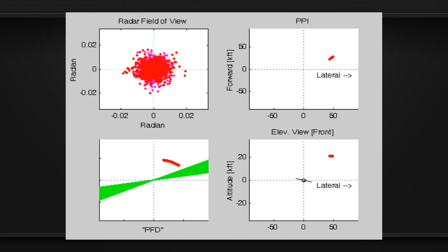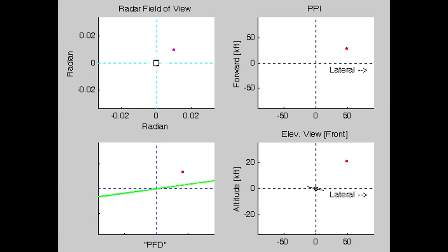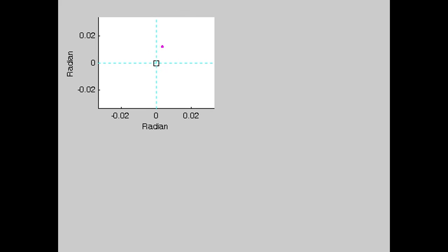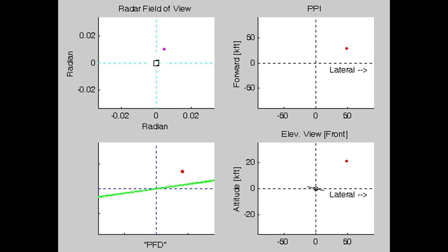Suppose imperfect antenna pointing is the only reason for dot off crosshairs displacement. The next one you're about to see is with RMS degradation from scintillation or other similar sources set to 0. Here's the rerun. As you'd guess in advance, we're letting the antenna sightline go all around, but compensation ensures that the total error will stay as 0 throughout. After what you've seen before, there aren't any surprises here.